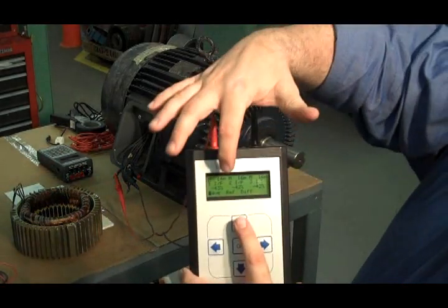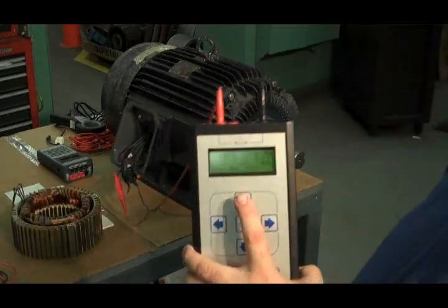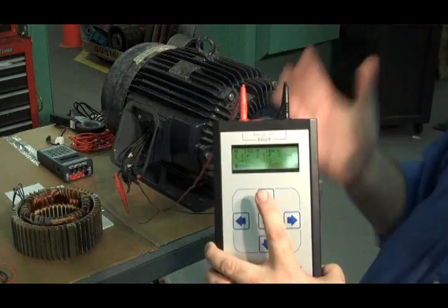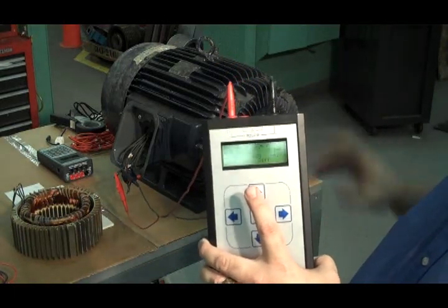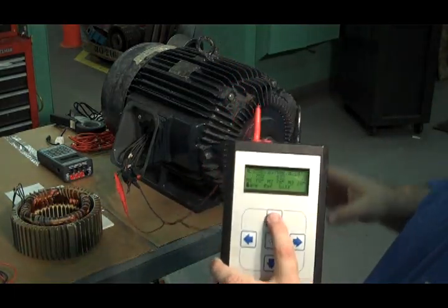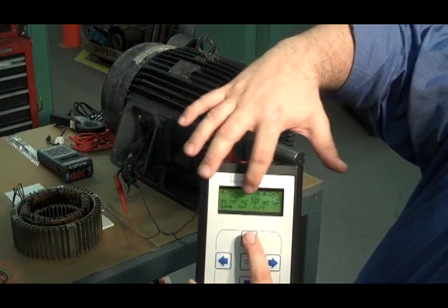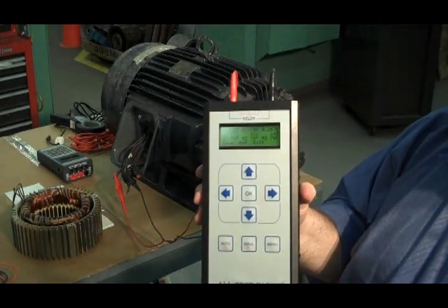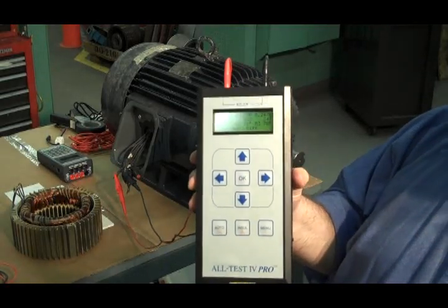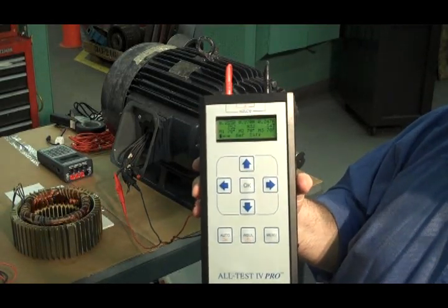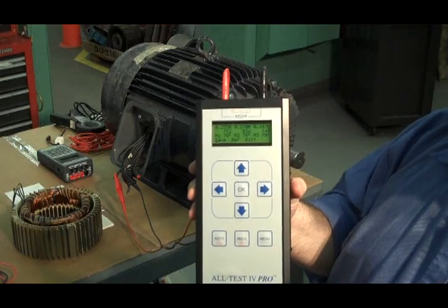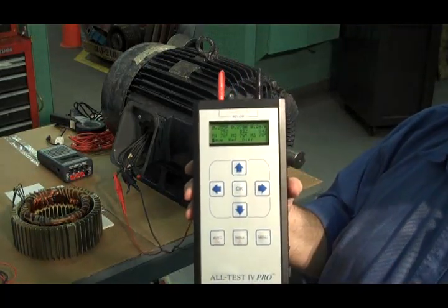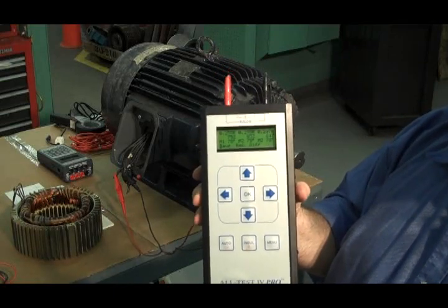Now, while I'm down here, minus 43, minus 42, minus 42, those are the current frequency response. Those are within plus or minus 1 of each other, so that means I don't have any winding shorts. And if I scroll back up, 78, 78, 78, that's the phase angle, again, all within plus or minus 1, meaning, again, I don't have a winding short. So if both of those are bad, I've got a turn-to-turn short. If the phase angle is good, but that current frequency is bad, that's a coil-to-coil short.